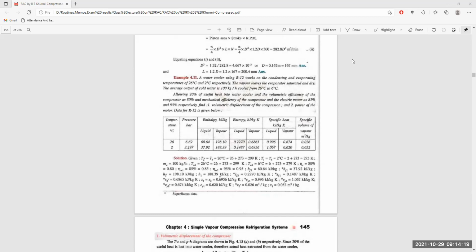So, at the evaporator, the refrigerant is converted from liquid to vapor by absorbing the latent heat from the surroundings of the coils through which it is moving. So the space inside the refrigerator is being cooled, because the latent heat for evaporation of the refrigerant is being absorbed from the surroundings of the coils of the evaporator itself.